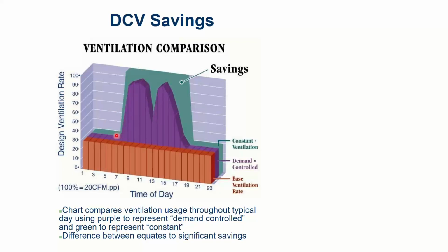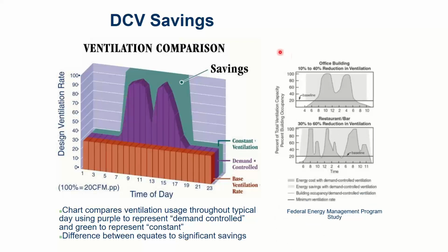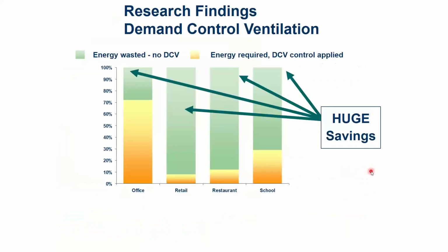Every office building in America gets this two-hump profile. There's numerous studies showing that. This two-hump profile for offices. If you work in an office where there's only 2 people that work there, okay, maybe you don't get that pattern. But if you get an appreciable amount of people, you always get this pattern. Restaurants always get a 3-hump profile. There's very predictable profiles we can look at and utilize those to estimate energy savings.